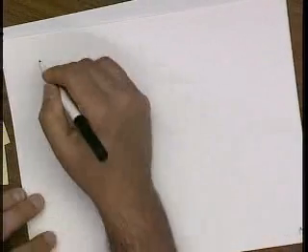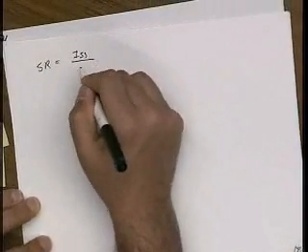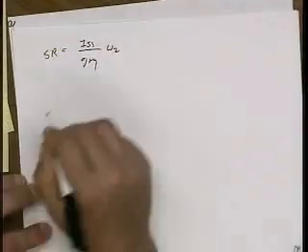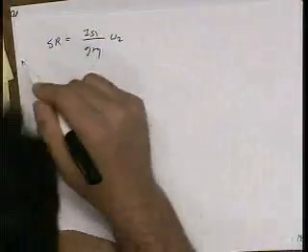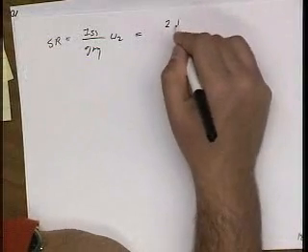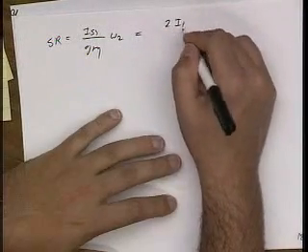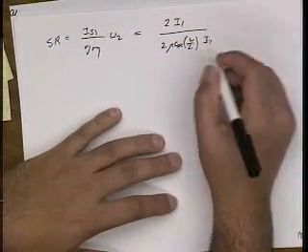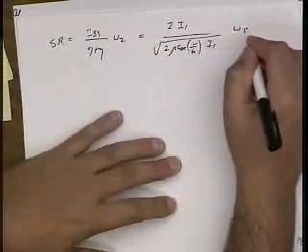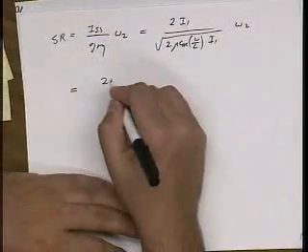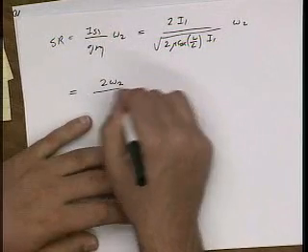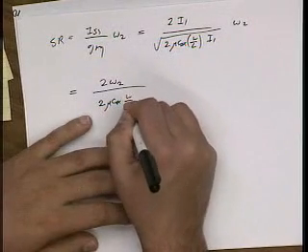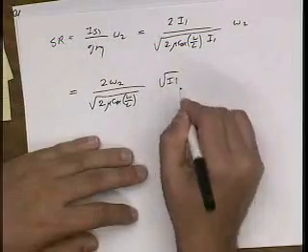All right, well, what about a MOSFET? Well, one of the advantages of a MOSFET is it naturally has a higher slew rate because it naturally is a dog when it comes to gm, right? Naturally, the gm is much lower for a given current. So if I substitute here for gm, gm goes like square root of current, and so I get an equation that looks like this. These are all kind of constants, and then this is a term that goes like current.